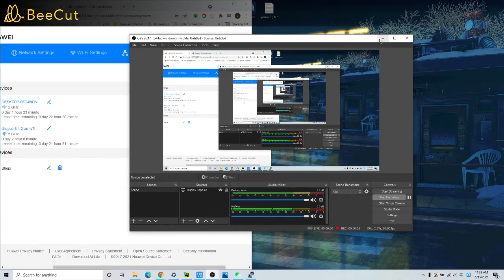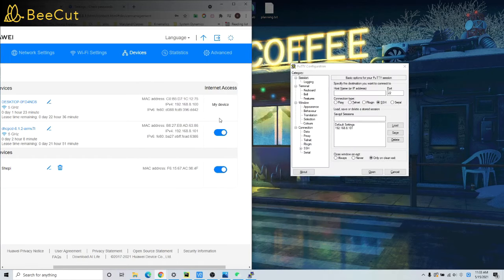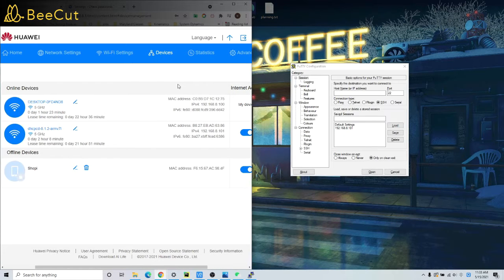Raspberry Pi is powerful, but if you connect it to a monitor, it's going to slow the Raspberry Pi down, and we lose remote control of the robot. So here I use SSH to connect my PC and Raspberry Pi. With this router manager, I can check my Raspberry Pi address and PC address. So this is my Raspberry Pi address. Put it into PuTTY, just type it.